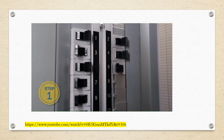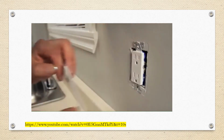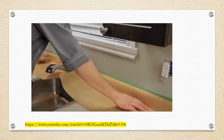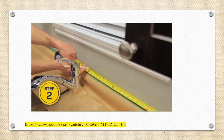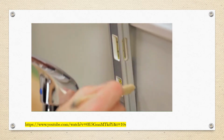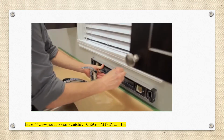Before you start, switch off the power to electrical outlets and take out decorative wall plates and other accessories anchored to the wall. Protect the countertop and other surfaces. To determine the layout of the mosaic tiles, draw a vertical line in the center of the area to be tiled. Then, draw a horizontal line to mark the position of the first row.